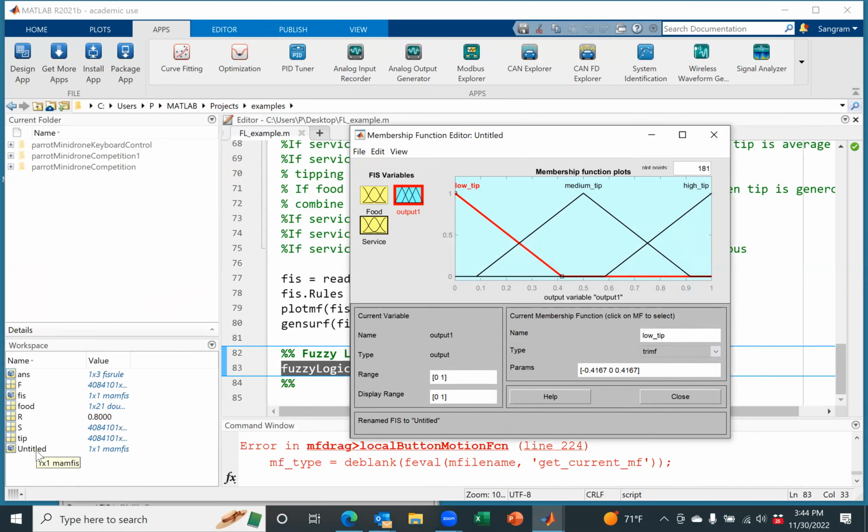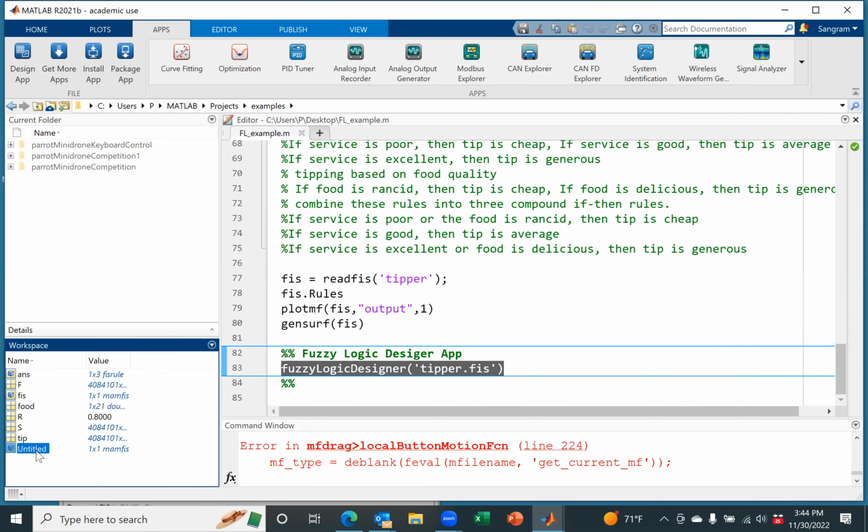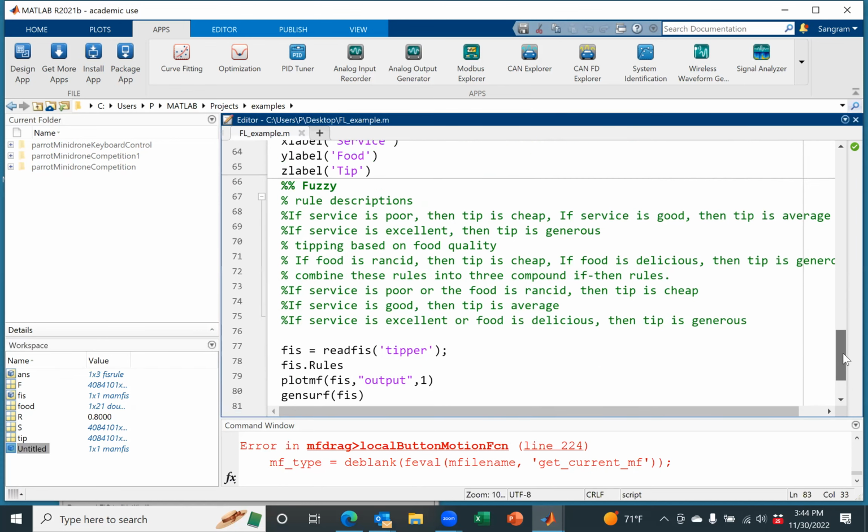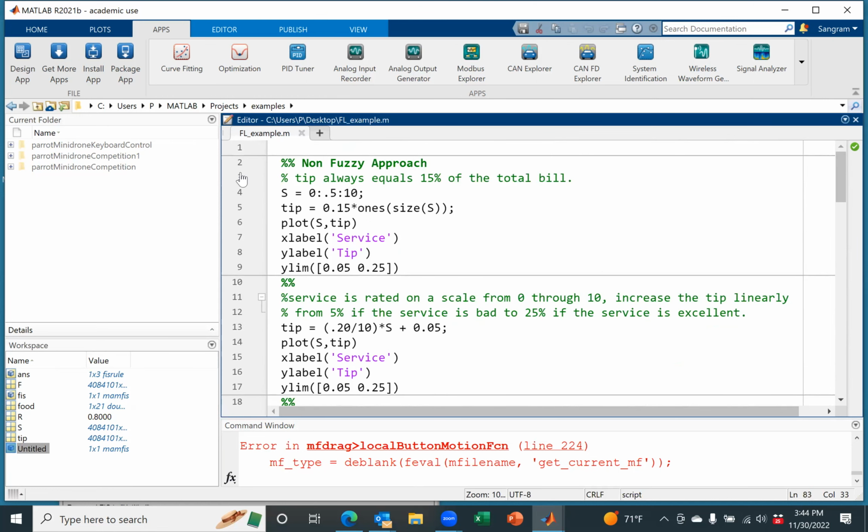So you can see that this becomes a fuzzy logic object that you can import and use in Simulink or any other code that you are using, and that can be used to control maybe a robot or to fuse the sensors, accelerometer, gyros, or combine data based on the LiDARs and the IMU or some odometry. So this is how you would use the fuzzy logic.